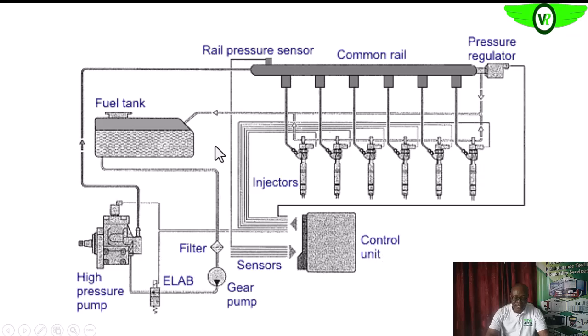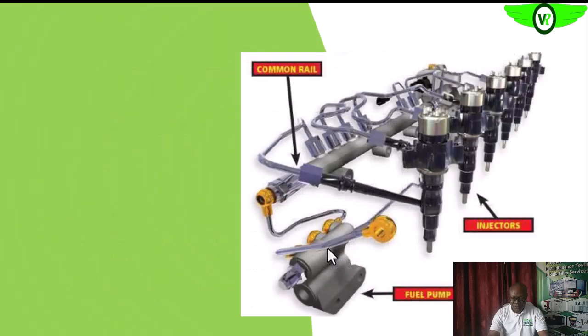And you see that it is also tied to this common rail or common header, okay, that also looks at the pressure at this common header, because if this is not delivering the right pressure, these will not be pressurized to the right level. So we have seen the function of the fuel system is to deliver fuel at the right pressure to the combustion chamber, to each of these cylinders, as and when it is needed in each of these cylinders, okay. So this is a summary of the fuel system from the pump through the common rail to the nozzles. Are we getting it?